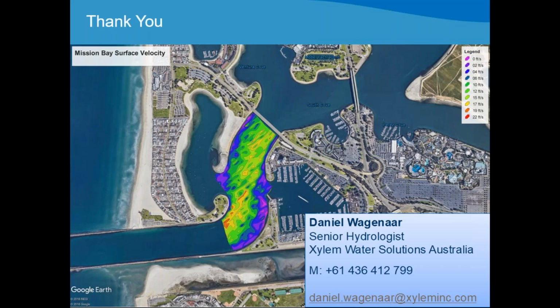Okay, Daniel, is it preferable to have the S5 mounted flush with the bottom of the hydro board, or is there a benefit in having it project 10 centimeters below? It depends, and I'm going to speak here with regard to all instruments. It depends on what the flow conditions are. If you have debris on the water surface, air bubbles, even, and I've seen cases in the desert where there's a lot of sand on the edges and the wind is blowing, that we get dust, very fine sands lying on top of the water surface. And that starts to accumulate on top of the transducers. And that will definitely impact your measurements.